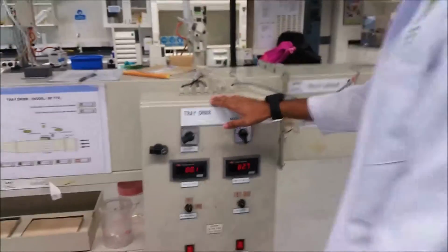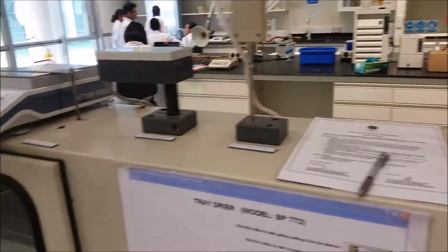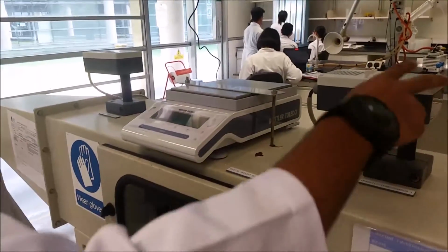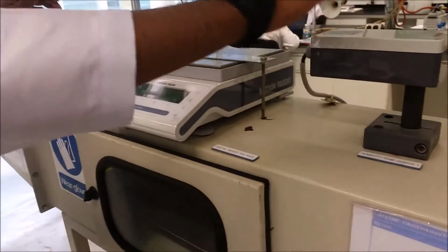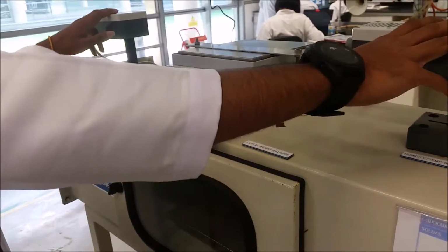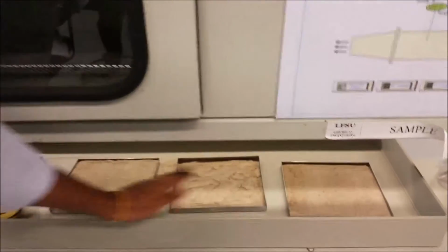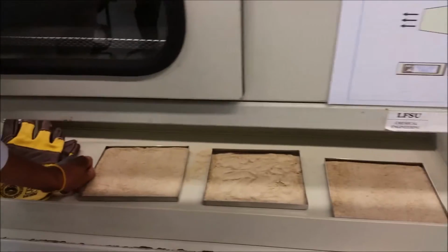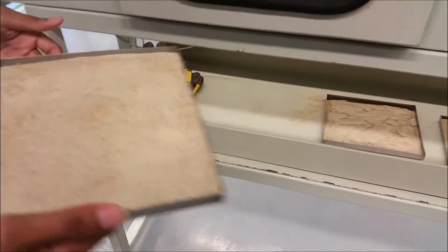Besides this, you can see the velocity transducer here. This is to measure the velocity of the air flowing inside. While these two are Rotronic sensors, which you can use to calculate. You have sensors for humidity and temperature control for the dry bulb and also the wet bulb. Besides that, this is our material. We can choose either one which has a smooth surface. Like this is not smooth, so we don't choose that. We choose this instead. And this is our sand, which is dry. So basically that's all.